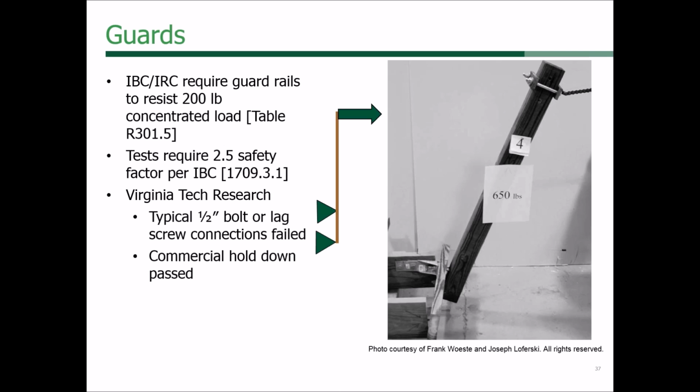If you'll notice, this test is really only testing the post, and is only testing the post going away from the deck. Technically the IBC and IRC say in any direction, but falling into the deck didn't make much sense, so they tested it outwards.